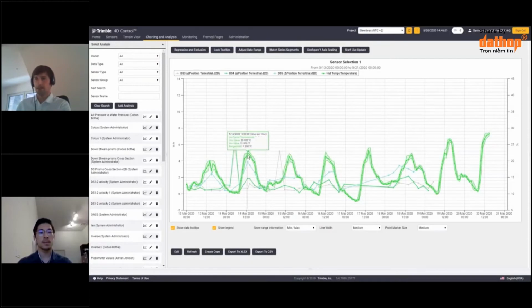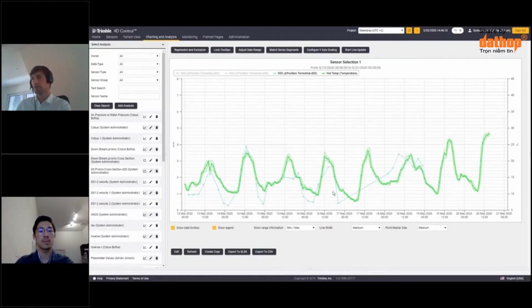There is really a spike. This is during the day, you see 12 p.m., and the lows here, so this is during the night. At the moment, it doesn't really say a lot. Let me maybe disable 2 of the 3 targets. And here you now nicely see, although there is not a lot of movement, we are really in the millimeter range here. We have a 2D displacement of my target DS5 up here, which really follows the temperature. So there is a nice way how you can analyze data, and this is an example to demonstrate that the 2D displacement really correlates with the temperature change.